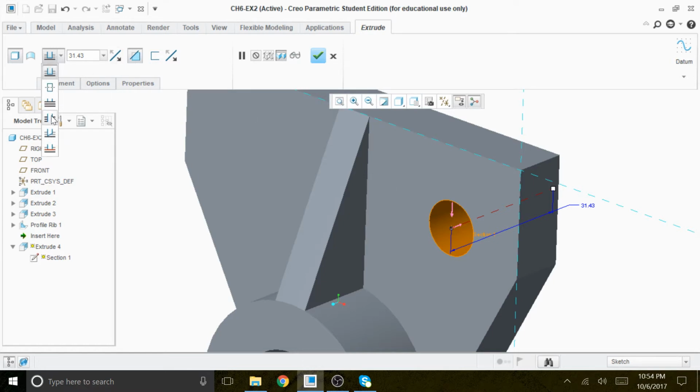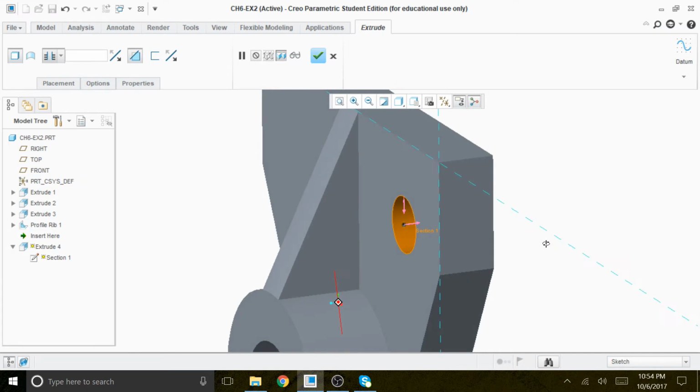All we have to do is click on extrude to intersect with all surface. Okay, all right, beautiful, everything is nicely done. And now we're going to go to finalize. That means build feature. This is called build feature, and we're going to just finalize it.